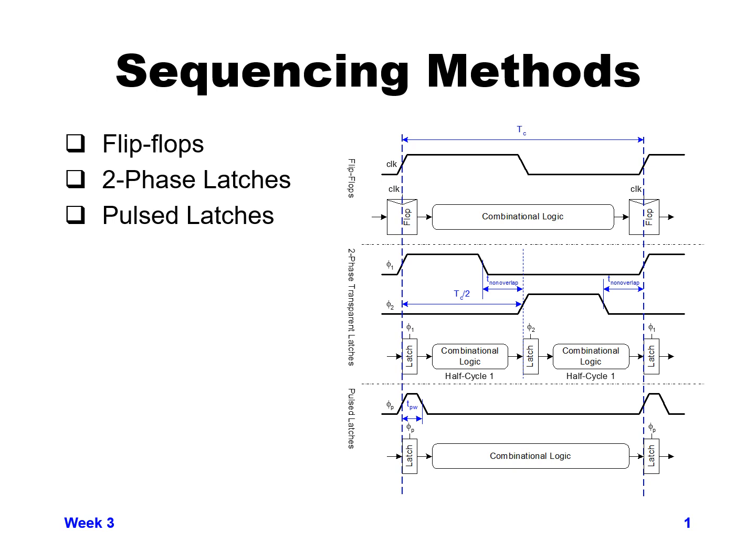And so this can be a way, sometimes people will use pulsed latches instead of flops because latches have less delay through them, they have less gates inside of them, and so they take up less area. There are downsides to this as well, and we'll go into that a little bit more in upcoming foils.